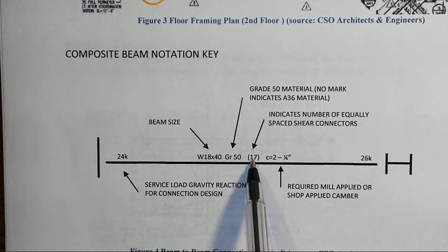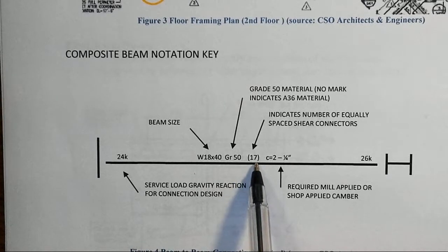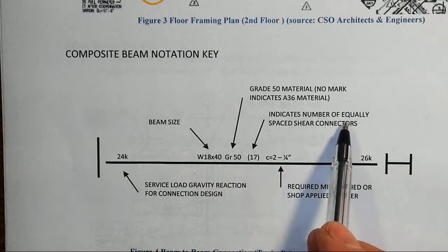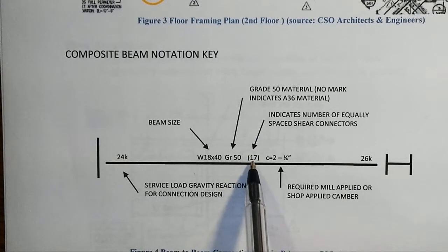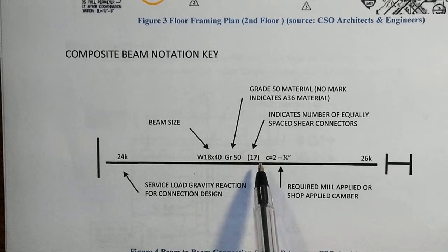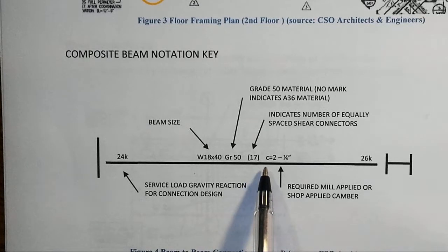And then in this case, actually, the beam and the floor are composite together. That we have a steel beam and a concrete deck with a metal pan that forms the bottom portion of the slab. And there's a number of shear connectors. They look like bolts that are welded to the top of the beam that are then embedded inside the concrete. Or really, they're welded, and then the concrete is placed so that they are embedded together, right?